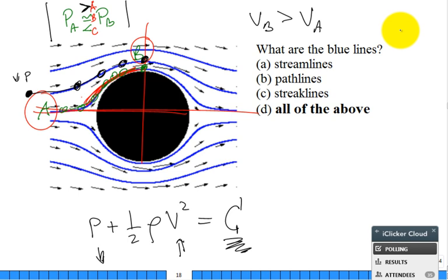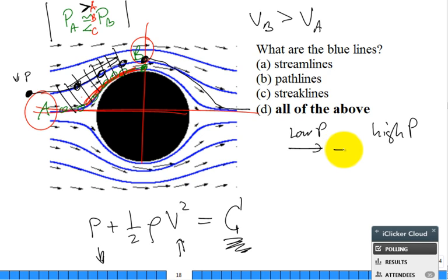If you don't understand that concept, it is not going to help much on the next concept, because what's happening coming back over here, the pressure's high, and it's going down, down, down. It's pushing the flow. It's what they call a favorable pressure gradient. If I have fluid at high pressure flowing in the direction of low pressure, that all makes sense. But can you turn it around? Can you ever have fluid flow from low pressure into high pressure?